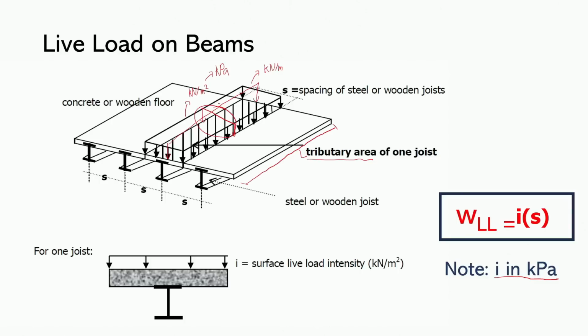However, this is not my interest because this distributed load acts over the spacing. We are interested in the distributed load that acts over the span or the length of the beam. And so ito yan. Again, hindi ito yung interest natin kasi hindi naman ito yung beam natin. This is our beam. Let's say, ito yung x-ray niyan. Diba? Ito yung length ng beam. So, erase ko to. And then, meron tayong figure for you to internalize why we are multiplying this by S.